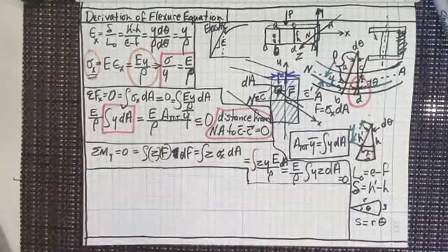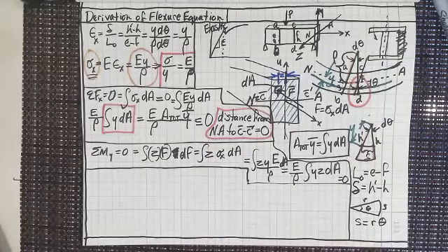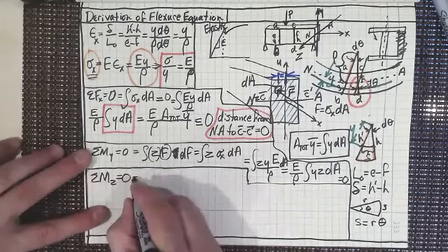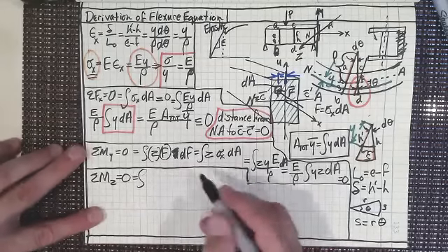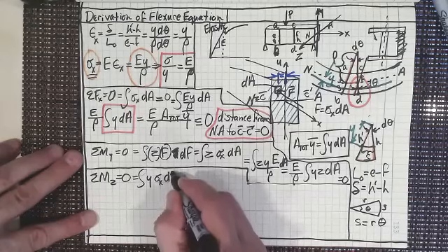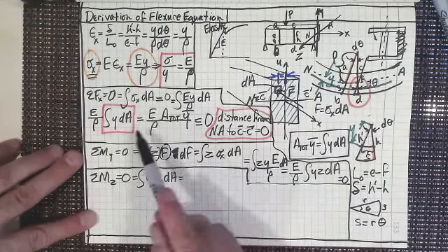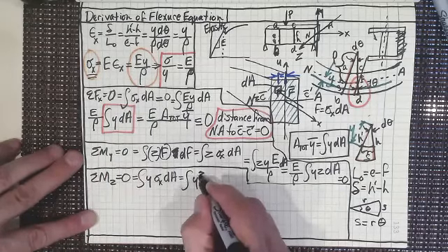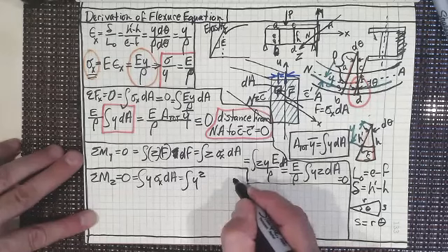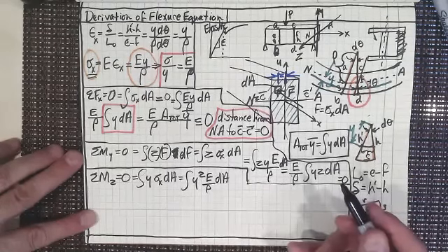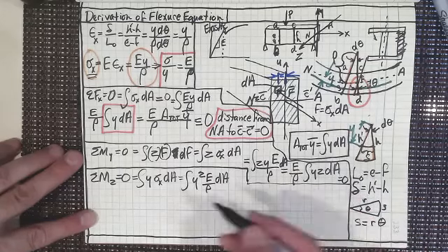This is the most important thing because we've looked at moments of inertia about the y-axis. So now I want to look at moments of inertia about the z-axis. And of course that, just using what we had before, is going to give me y times sigma sub x dA. And when we replace it with what sigma sub x is, what we end up getting is y squared times E over rho dA. I think everybody can see what I can do with this.